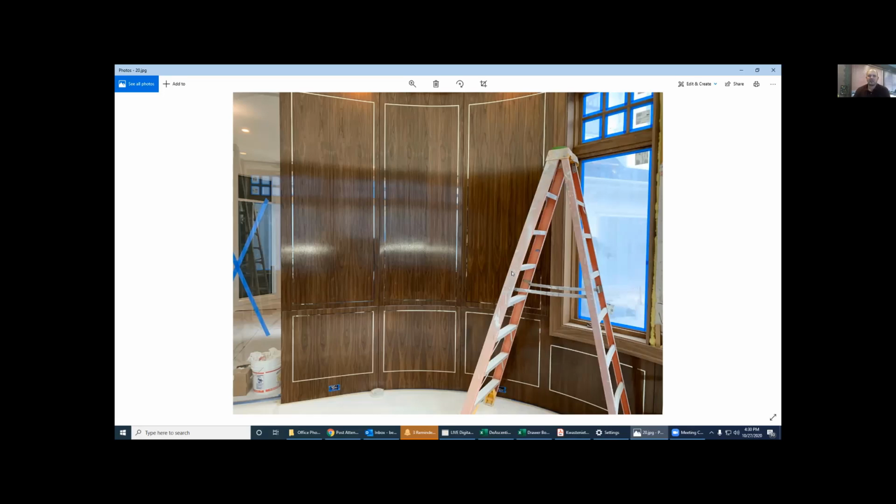For the metal band, we did create a parametric subassembly for routing all of the metal bands and the doors when they're on the flat. We did a lot of cabinetry with this detail. For those doors, we had a metal band report that exported with a 30 thou gap, so we had a little bit of play. That exported to a report, and we could outsource it. We ordered the metal bands out and cut the wood here in the shop.